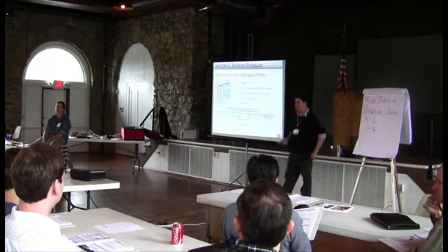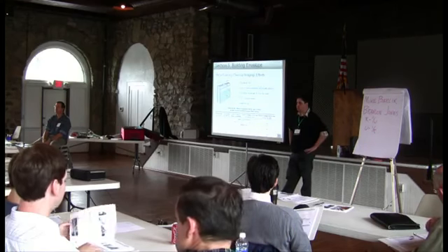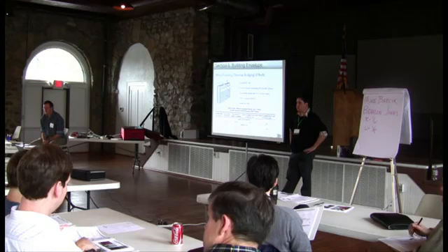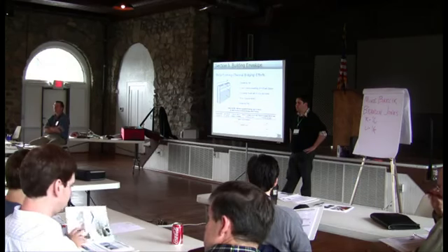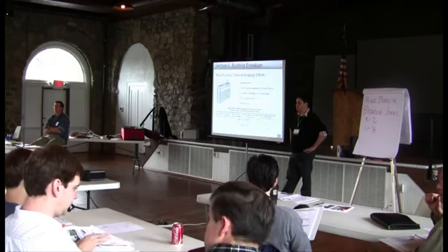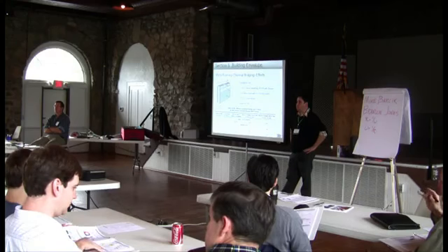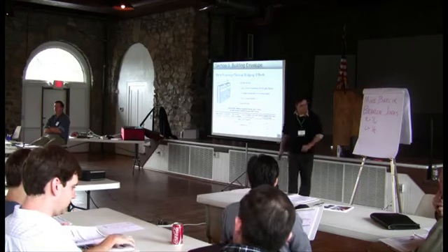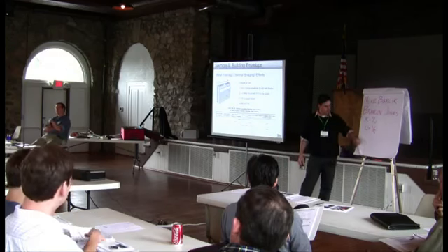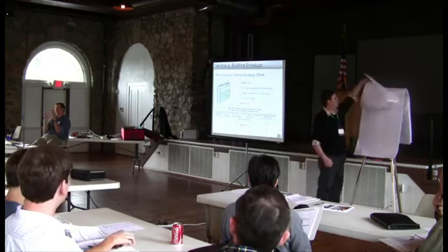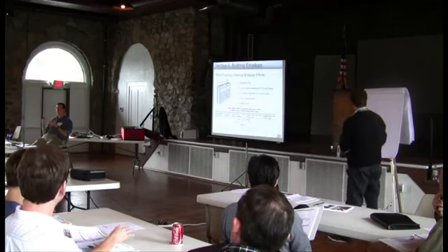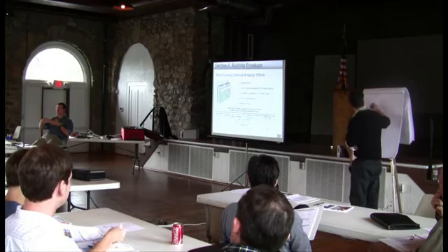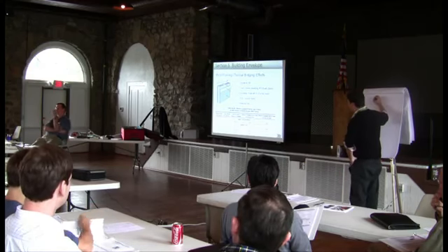Yes, sir. One of the things, if you have put up a metal building and use metal skin on the outside, and then you put a stud wall inside, you've got about an 8-inch air gap between the skin on the outside and the metal wall. So you really don't have that big a concern about the conductive value of the stud. In other words, if your steel studs are just there, basically holding up drywall, then that's fine. But you've got to have insulation, in essence, between the skin. We have some pictures of this coming up.